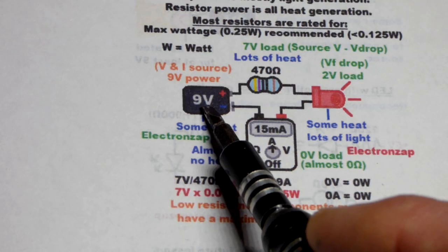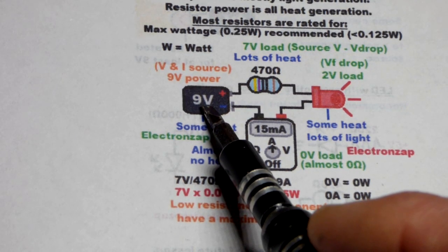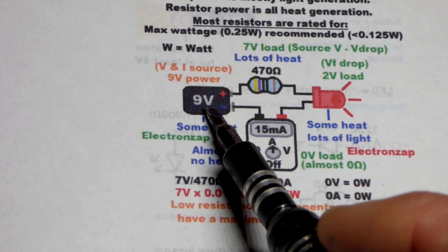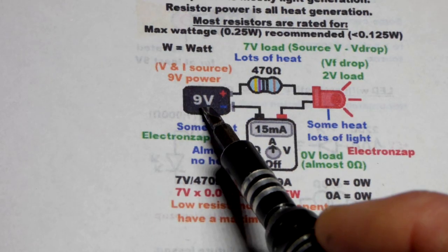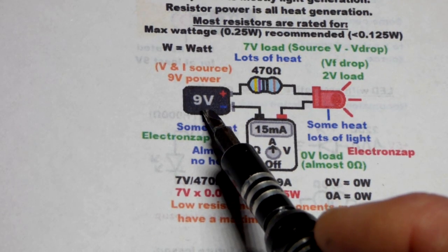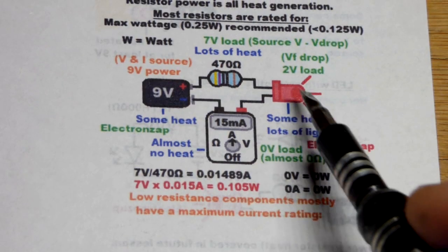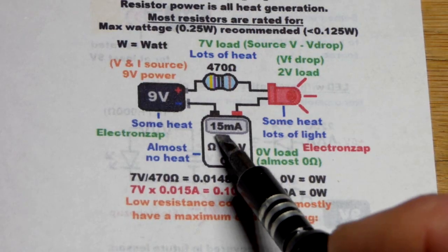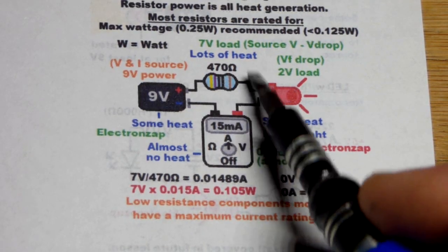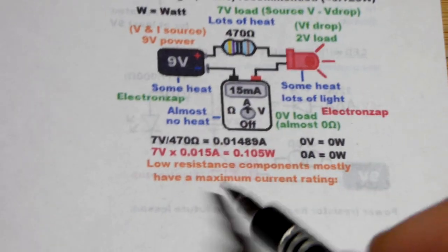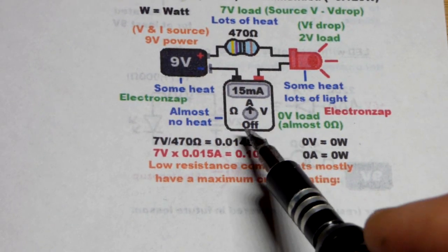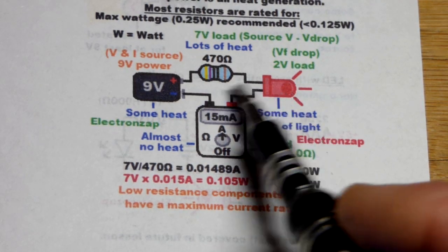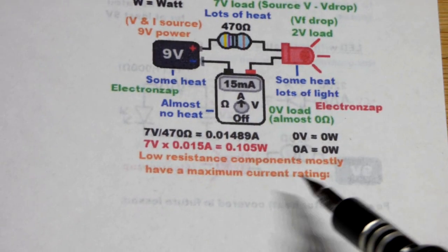So what we could do is get a voltage converter. There's a lot that take a higher voltage and will give you 5 volts. So, not quite half of what we got here, a little bit more than half, but somewhat close. Then we would have 3 volts across the resistor. Instead of 7, we could use a lower value resistor to get about 15 milliamps of current, and it would have less waste heat. So that's one way you conserve power. Try to get the voltage as close to what the load needs, just a little bit more. And then by limiting the current, you waste almost no power.